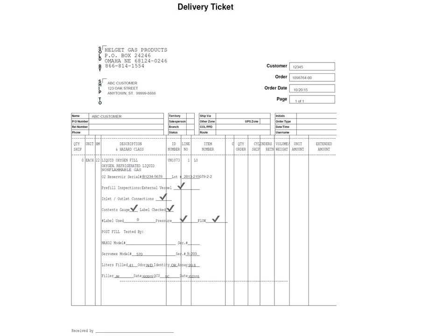Then you have the post-fill, and it will put down tested by. What that is asking is, how did you test that liquid oxygen reservoir? You either tested it with a Max O2 or with a Servomex. Depending on how you tested it, that's the information you're going to enter. In this particular case, this unit was tested with a Servomex model 570. The Servomex also had a serial number, S as in Sam 203.